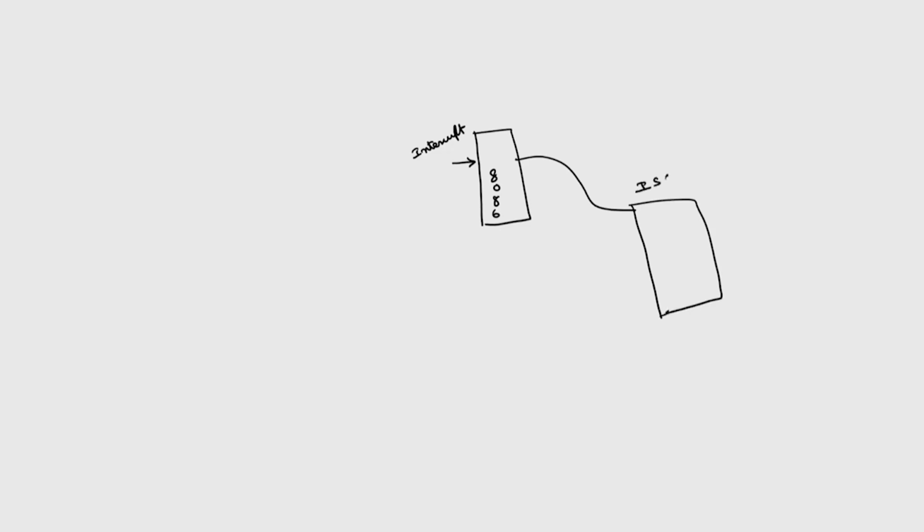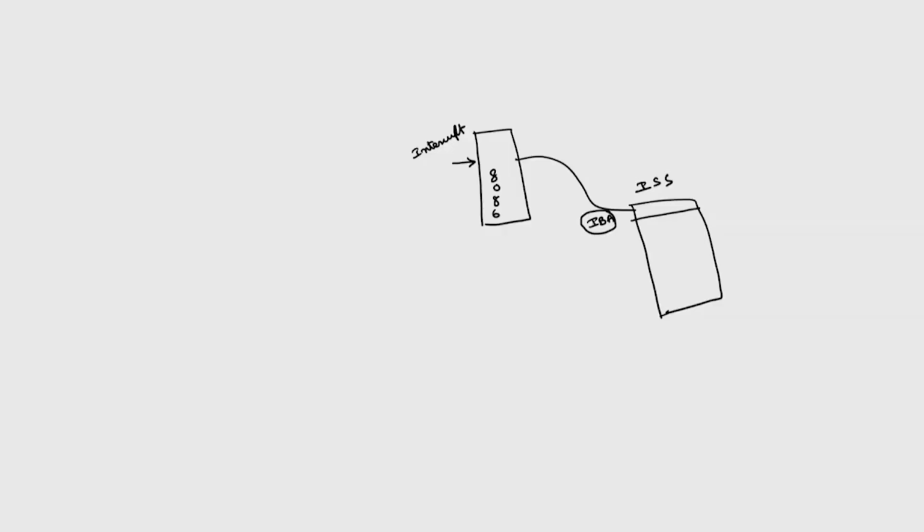Its first address is called the interrupt branch address. This interrupt branch address will be different for different IRs. Totally we can have 64 different IRs in cascading mode. So this will be one of the type 0 to type 255 interrupts.